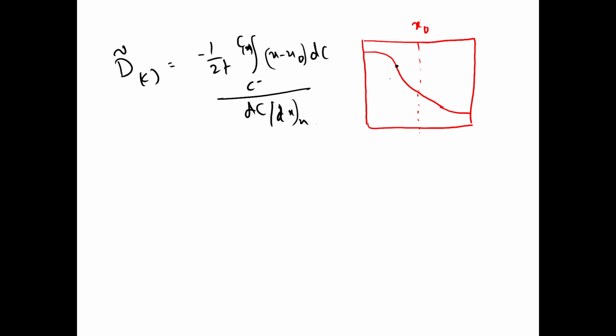So if you want to determine the interdiffusion coefficient at point x A, first you need to determine the gradient, the slope of this. By calculating the slope at this point, you can determine the ∂c/∂x, and you know the time value, how long you have carried out the interdiffusion annealing.